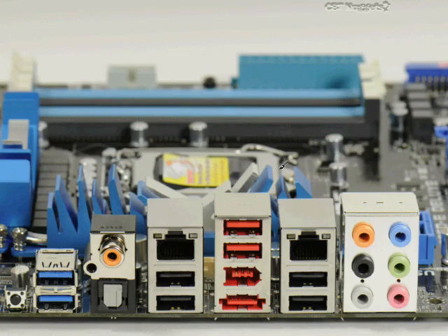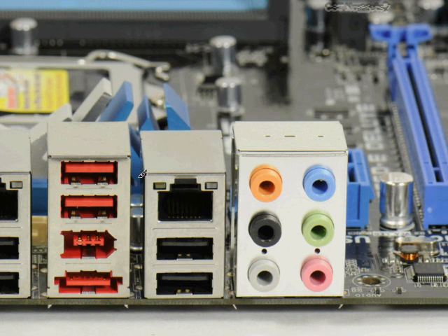And if we take a look at the motherboard rear connections, we can review those just briefly here. Again, the green is normally going to be output. Normally your speakers plug in there. A lot of the speaker cables now are also color-coded to match this. Pink is usually your input for something like a microphone, and then this would be the line in. These are the three that you'll see on most motherboards. You might not see these other three, but you'll usually see at least these three, and this would be the input, like I said, for something like a CD player or a tape deck or something else where you wanted to put sound into the motherboard that you could then record off of.